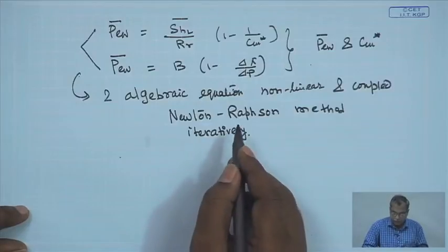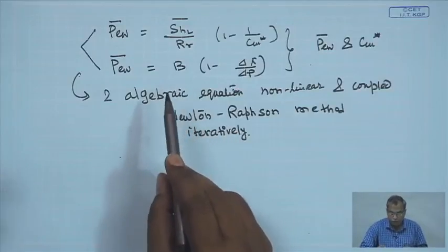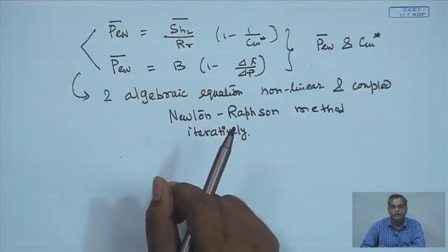Therefore, what we have seen in this class is how to solve the detailed two dimensional model for osmotic pressure controlled filtration, and once you get the concentration profile, if you hook it up with the transport phenomena through the porous membrane, then you will be getting the system performance.